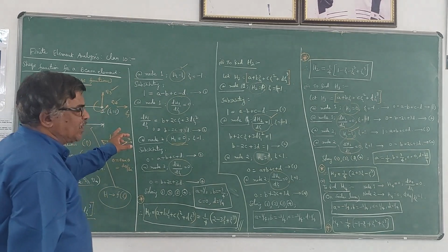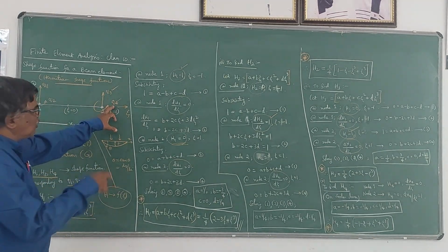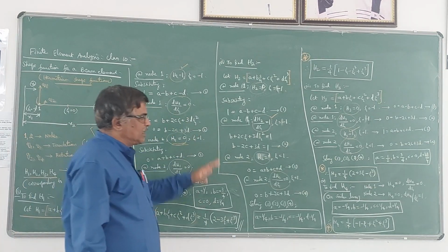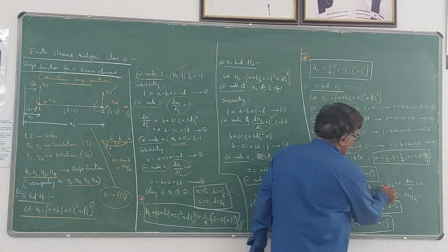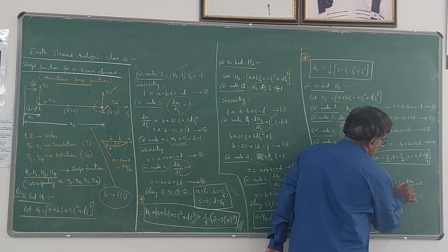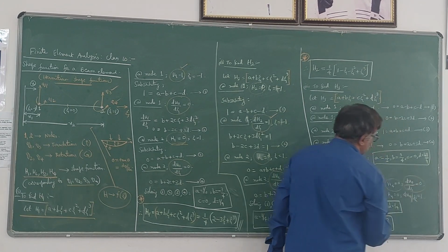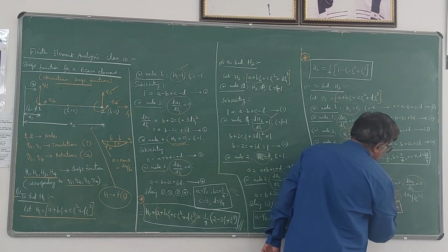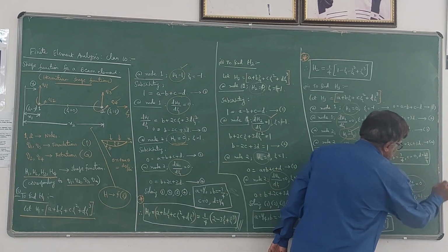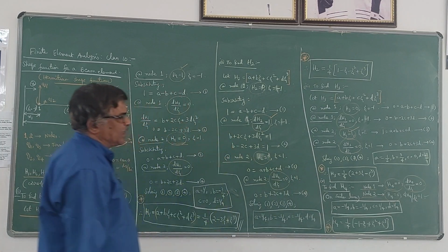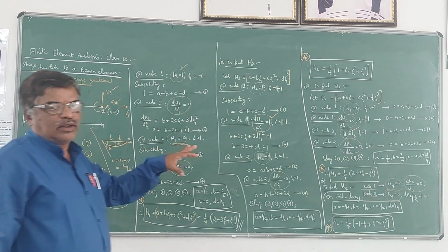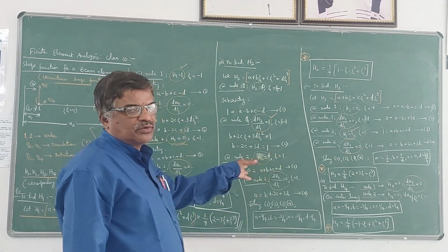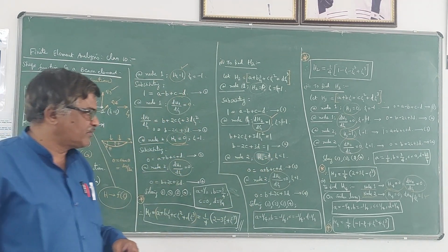So when you are finding Q4, H4, the other three you have to take as 0, corresponding to Q1, Q2, Q3, you have to take it as 0. Please note here, I have written H4 is equal to 0, dH4 by d zeta is equal to 0 at node 1, whereas at node 2, H4 is 0, but dH4 by d zeta is equal to 1. See the order here, so when you remember the order, you can easily differentiate and substitute the values, and you can solve the set of equations.